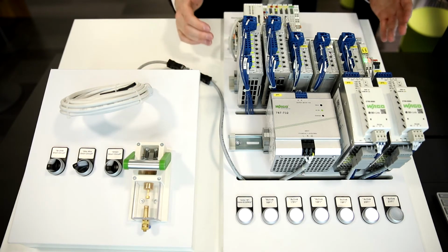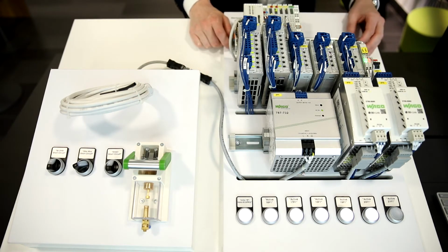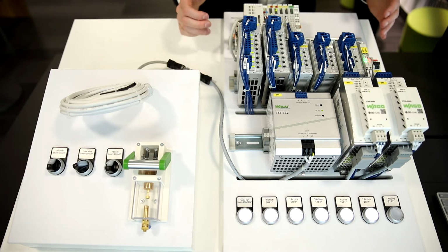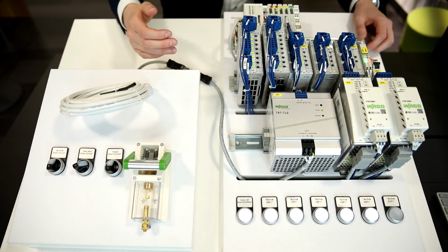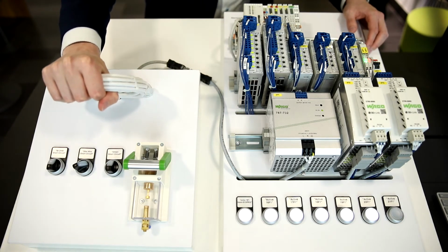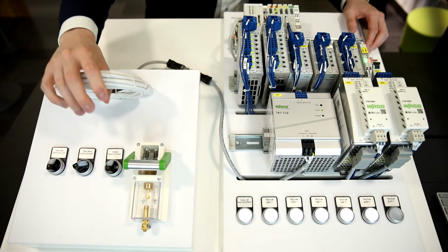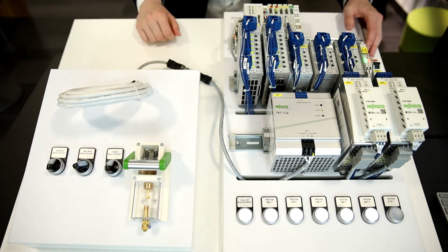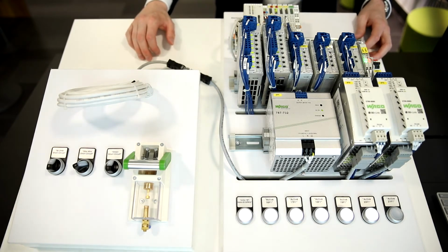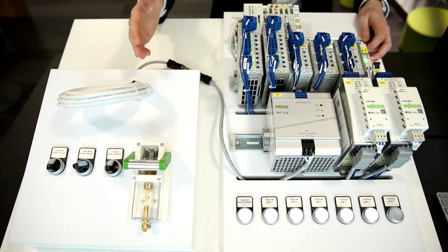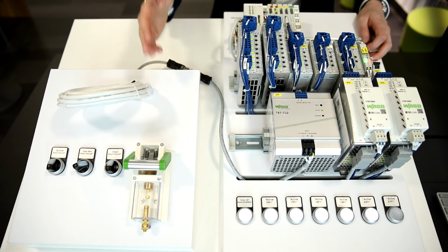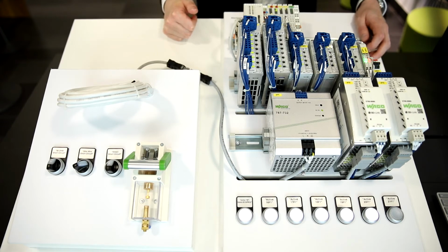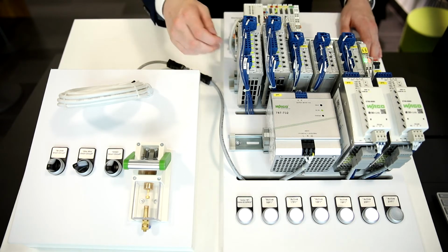So we see we have no trigger on the miniature circuit breaker. It depends on a longer time until it will trigger. But what we can now feel is that the cable gets really warm. This is a bad case for your production machine, because then you can have a cable fire, or the cable would burn.